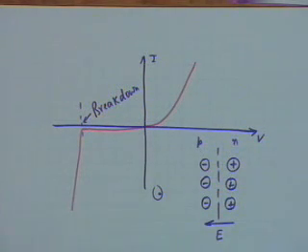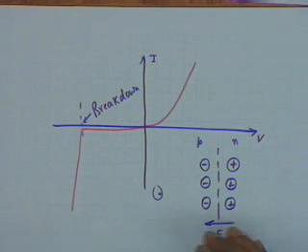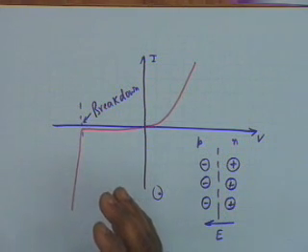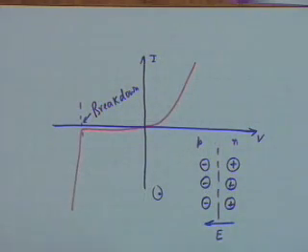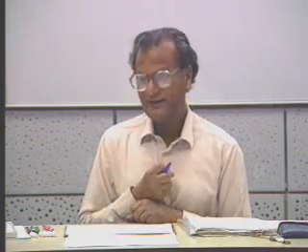Therefore, what it causes is an electron hole pair generation, and therefore the number of carriers available increases, and this onset is distinct. It's marked by a certain voltage. Beyond this, the electric field is sufficient to generate carriers as a result of its ability to draw electrons from a covalent bond. After all, a covalent bond also has a certain amount of binding force. If the attracting force cancels this, then the electron gets free and carriers are generated.